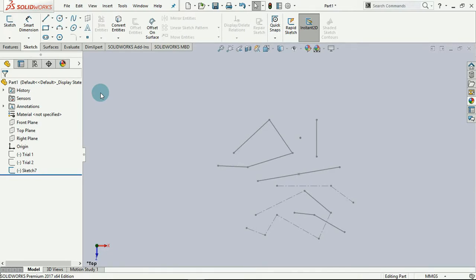Okay, I think I actually said you don't need a plane with the previous video when doing your 3D sketch. So you can select this drop down and click on 3D sketch. But be aware that this is not the usual method for creating sketches, so it shouldn't be your default method. However, sometimes it comes in really handy.